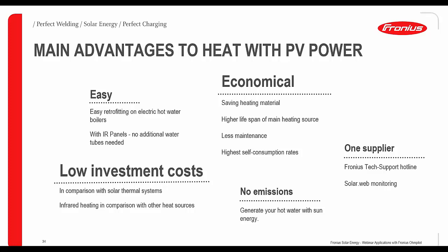The star point, you connect to your neutral, and then the three phases at the end points of this star. If there is any other triangle connection, then you can't use this heating rod for this solution because we need a 230 volts connection.